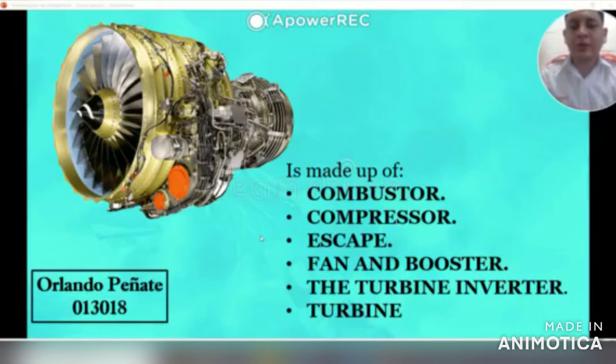The thrust reverser. The CFM56 is designed to support various reverse thrust systems that help to slow down and stop the aircraft after landing. Variants for the Boeing 737, the CFM56-3 and the -7, use a cascade type thrust reverser.